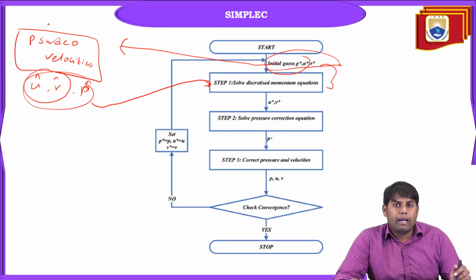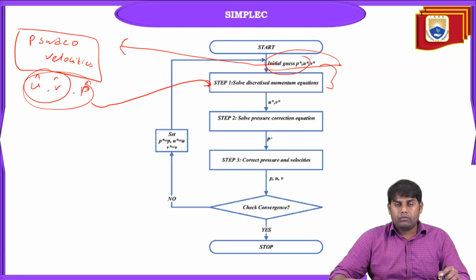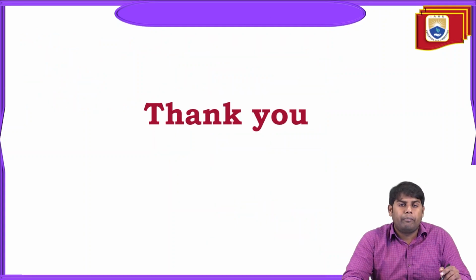So with this, what is happening? It will improve the accuracy. The remaining procedure is mostly the same. The major change is that we calculate the pseudo parameters, and with that you get some accuracy. So with that we have compared the SIMPLE algorithm, which is semi-implicit pressure linked equation, with SIMPLEC and SIMPLER.